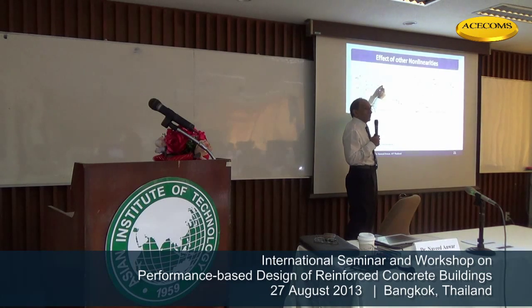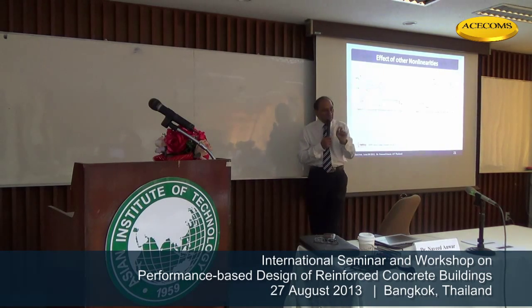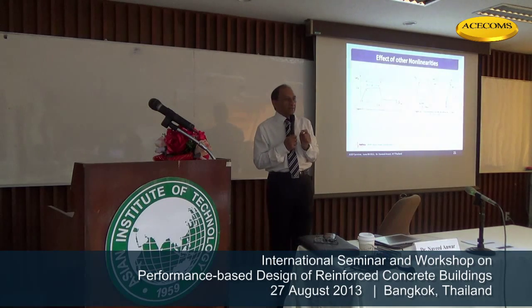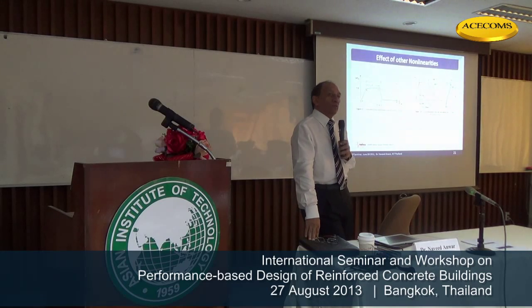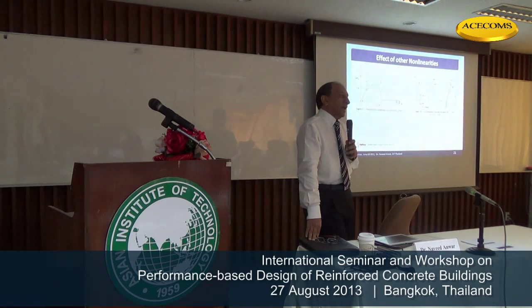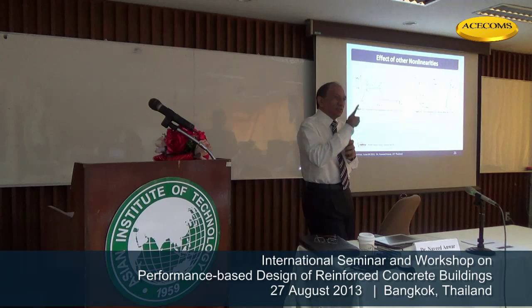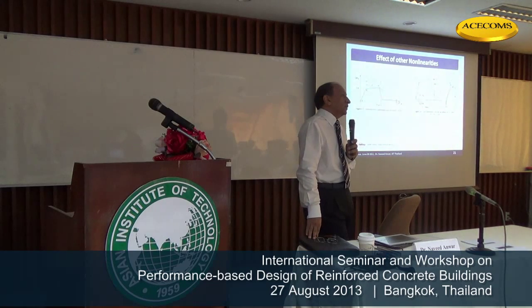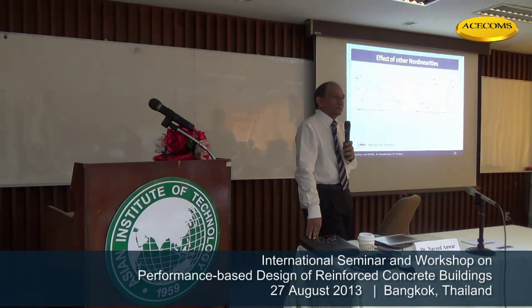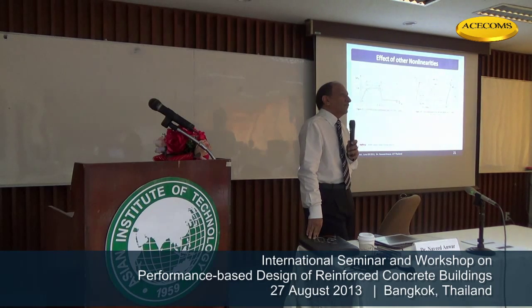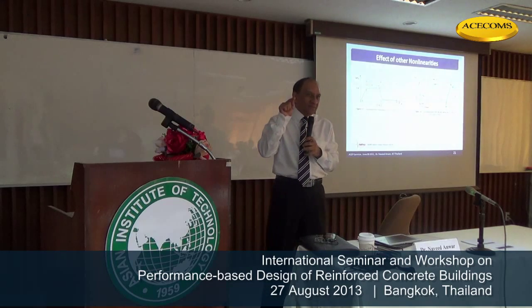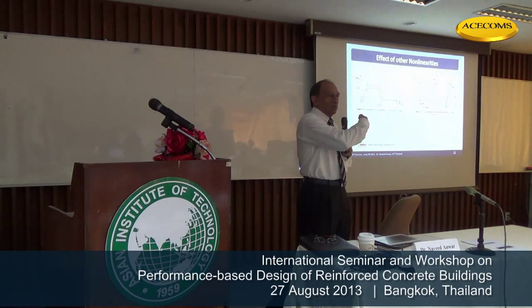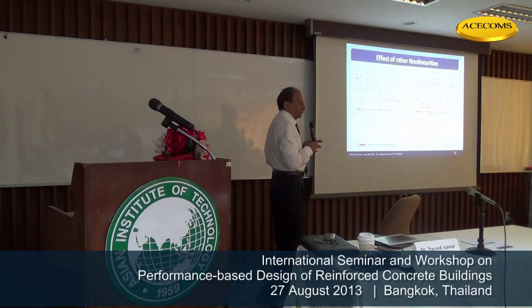It follows your specified curve. And this is where the control in modeling comes in, because this can be generated based on the actual provided reinforcement and confinement conditions. So each cross-section, each member, each beam can become unique, because each may have different reinforcement and different confinement and different spacing of stirrups, right? That can now be reflected in this curve.